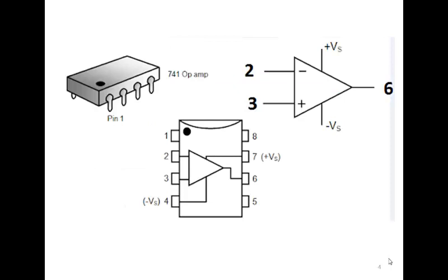We have introduced op-amps in earlier lectures, in which we concluded that an op-amp is basically an IC, and it has two inputs and one output, and two power supply connections. These two terminals serve as the input to the op-amp, and we can apply input on either terminal or at both terminals, that is V in 1 and V in 2, and we will get output from pin number 6. That will be the amplified version of these two inputs, and the gain of this amplifier is defined as the differential gain AD, and the differential gain of the op-amp is very large.